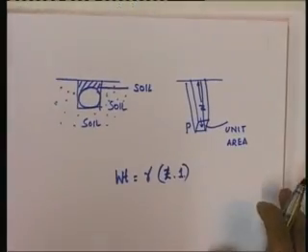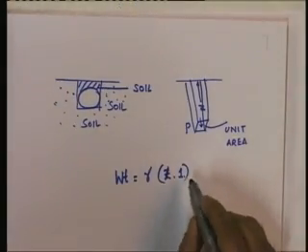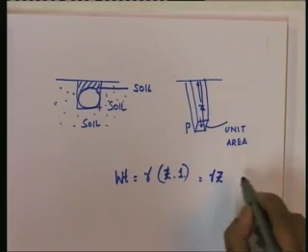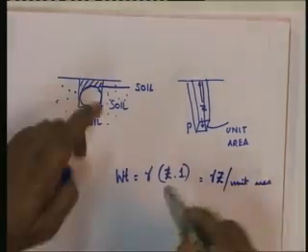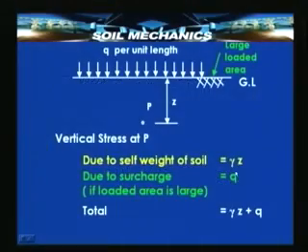Therefore, you find that this weight is equal to gamma Z, and that is the pressure because it acts on unit area. So, we have here the self weight of the soil which is gamma Z per unit area, that is the stress at point P. Now, we are applying a load here in the form of Q by constructing some structure here. Any activity on the surface, be it the construction of a tall tower, a retaining wall, a building, whatever the structure may be, let us say it imposes a stress Q.